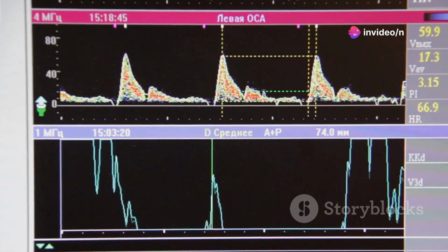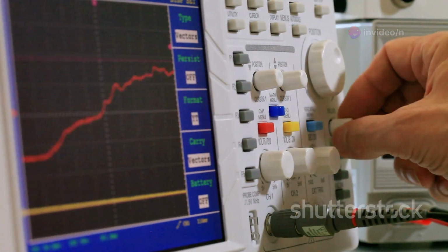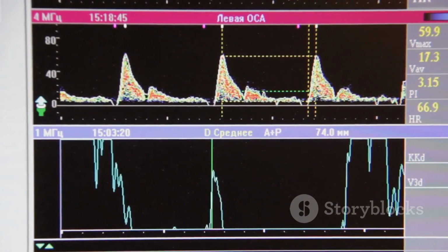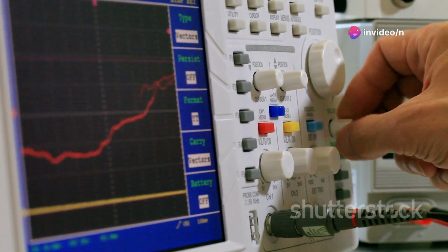First, divide the waveform into equal time intervals. Next, square the instantaneous value of the waveform at each interval. Then, calculate the average or mean of these squared values over one complete cycle. Finally, take the square root of the average value.